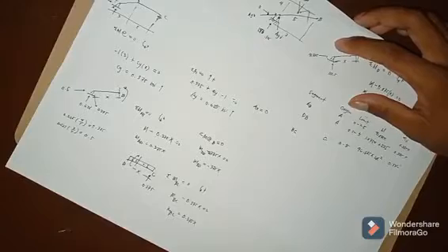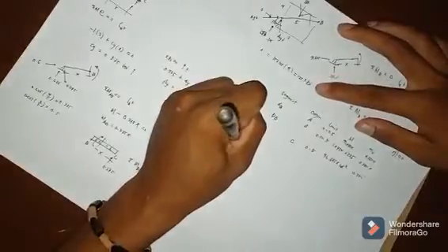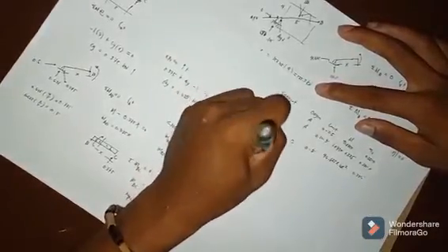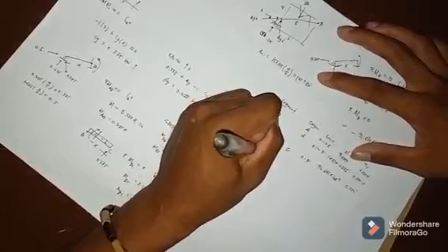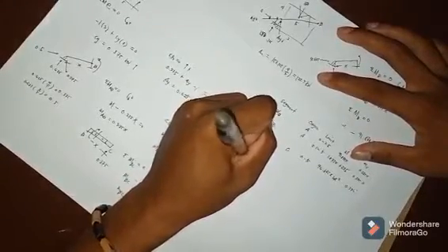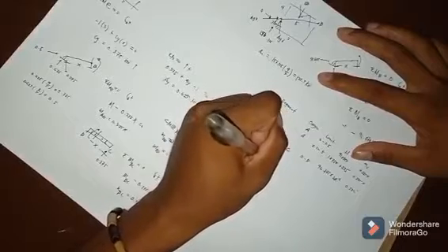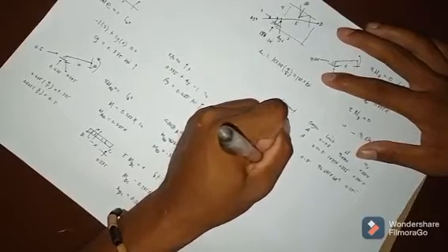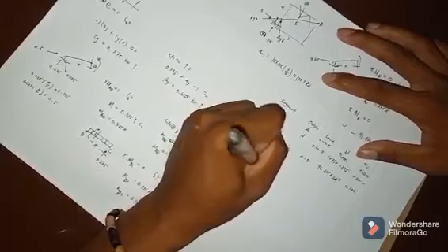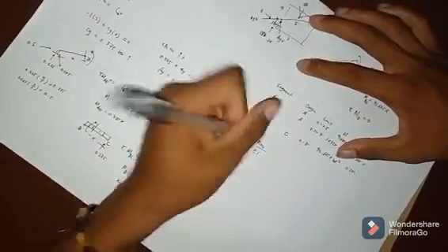So the last problem is we're going to solve the deflection at point B. Considering the formula, the deflection is equal to the integral over the limits of the moment in the real system times the moment in the virtual system divided by the EI, which is constant. So these are only the summation. We can put the summation here.